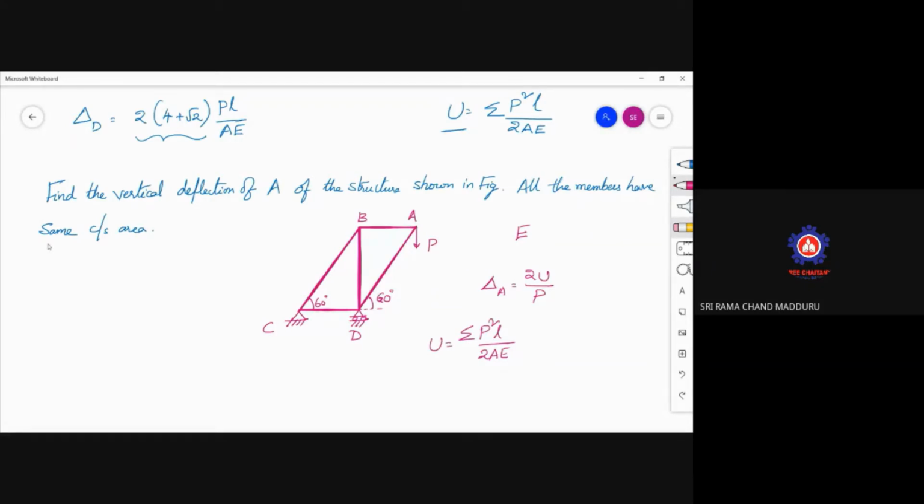So note this down and leave some space. I am giving you the answer. Please check whether you are able to get it or not. Using the equilibrium of joints, first calculate the reactions at C as well as D. After getting the reactions at C and D, you go joint by joint, taking the free body diagram wherever the number of unknowns is less than or equal to 2.